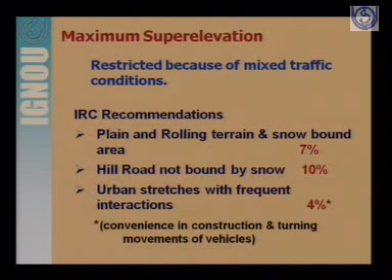In plain and rolling terrain and snowbound areas, the maximum super elevation has to be restricted to 7%, meaning 0.07. In hill roads not bound by snow, it may be up to 10%. In urban stretches with frequent intersections, the maximum limit is 4%.